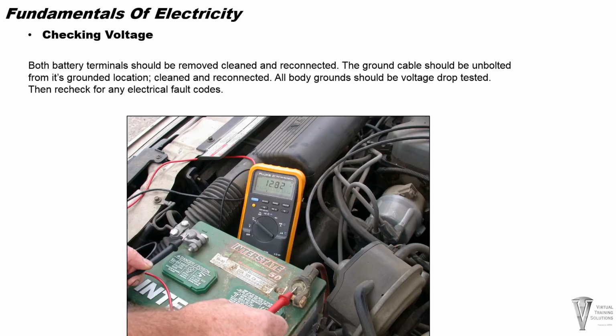Measuring voltage between 2 points in a circuit is called voltage drop. Remember, all of the vehicle's electronics start and end at the battery. Before doing any electrical tests, especially fault code and computer communication tests, know that a bad battery can also trigger an anti-theft lockout and lose radio presets. Before you do any of that, always go to the battery and verify that you have 12.6 volts or higher, standing still, not running. Make sure the clamps are clean, the wires are clean, and the cables are clean.